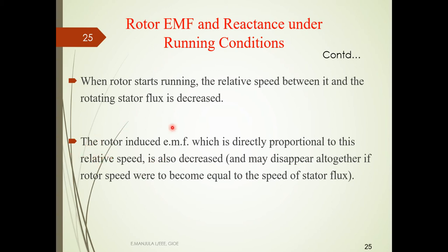Relative speed. So this rotor EMF is directly proportional to the relative speed. As the relative speed decreases, the EMF induced in the rotor will also decrease, and may disappear altogether if the rotor speed were equal to the speed of the stator flux. That is, if the rotor rotates at synchronous speed, then the EMF induced in the rotor is equal to 0.